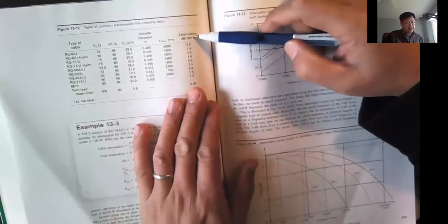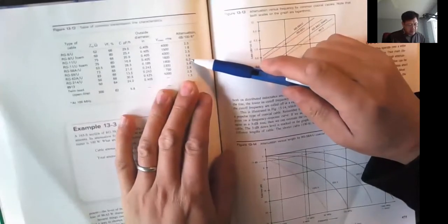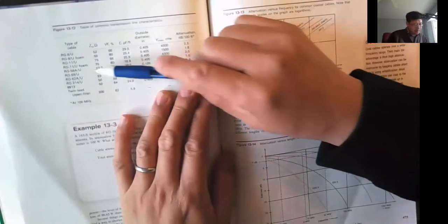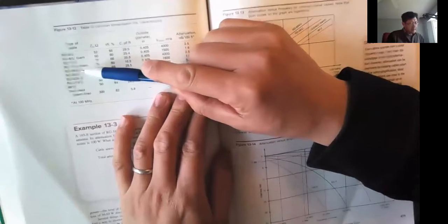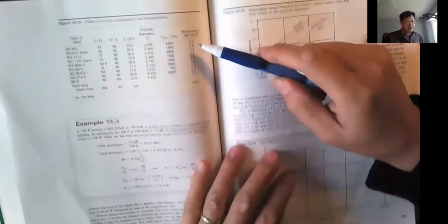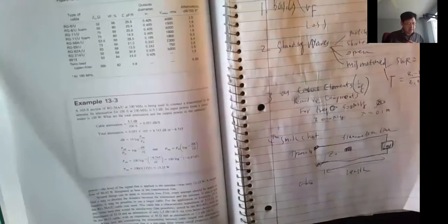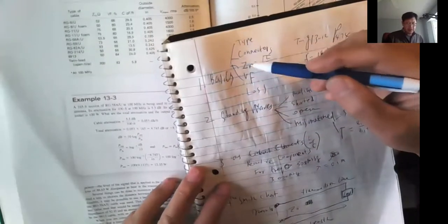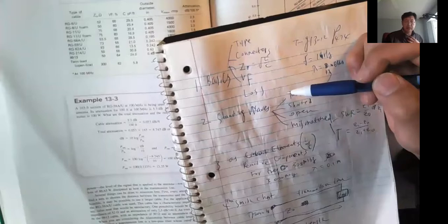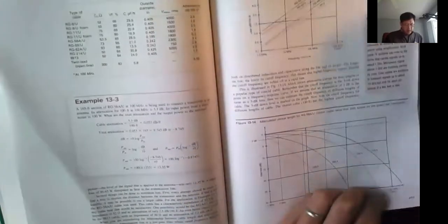So that's for 100 feet of cable, which gives you an idea. For example, the worst one will be this cable, called the RG58A/U. That will be the worst performance transmission line as far as energy loss. So after 100 feet, you get some energy loss. So those are the five topics for the first section of transmission line.